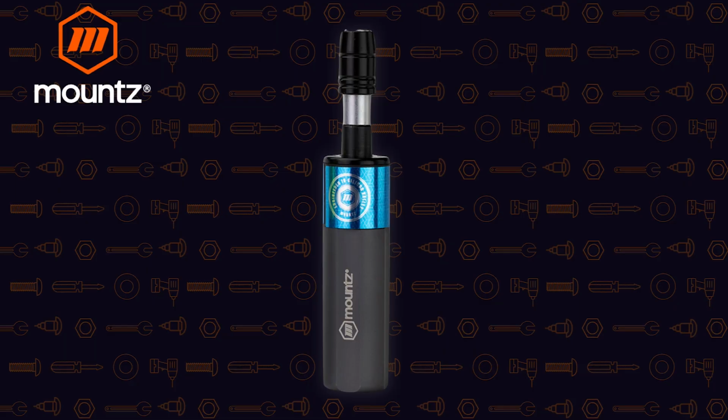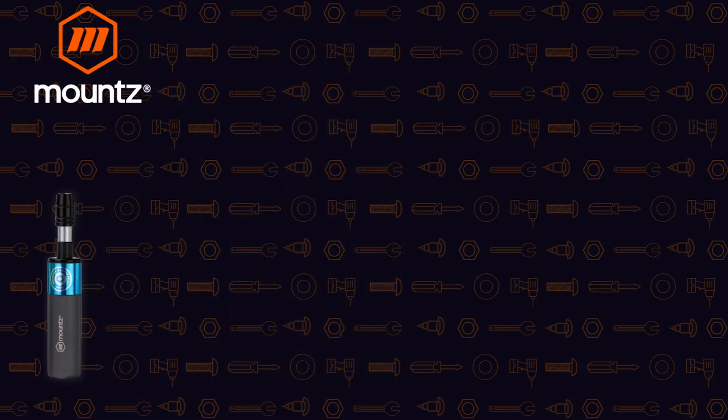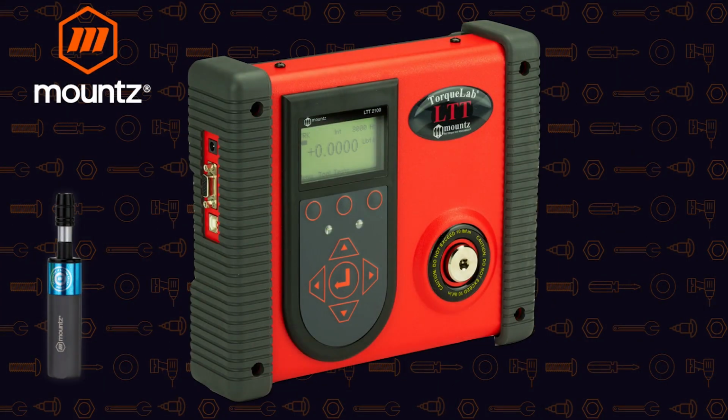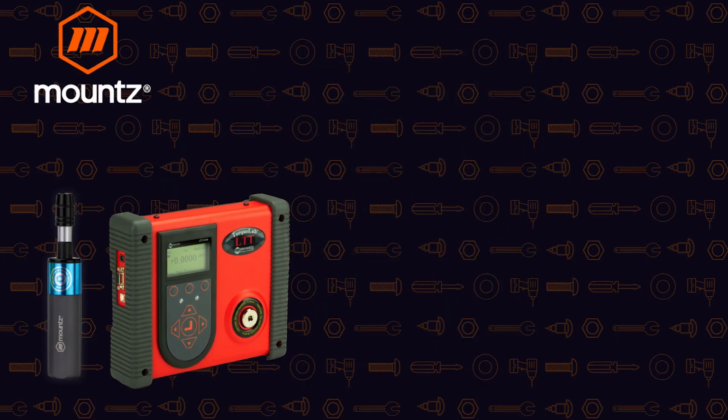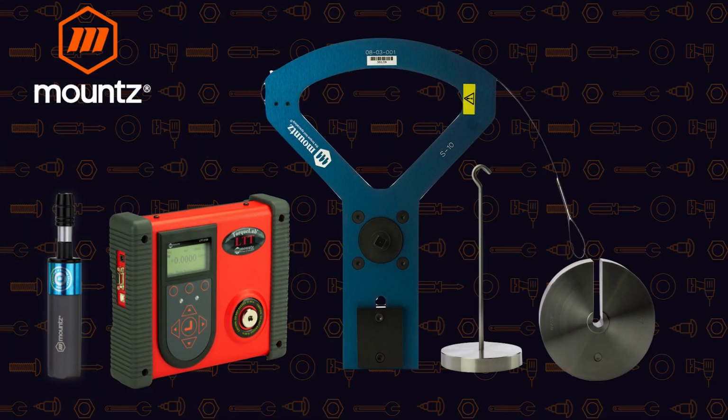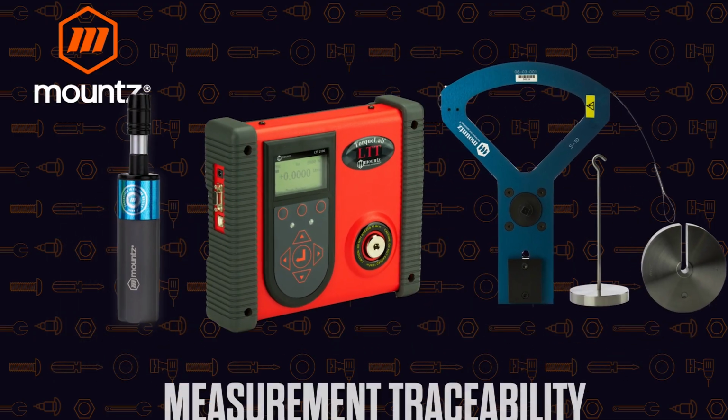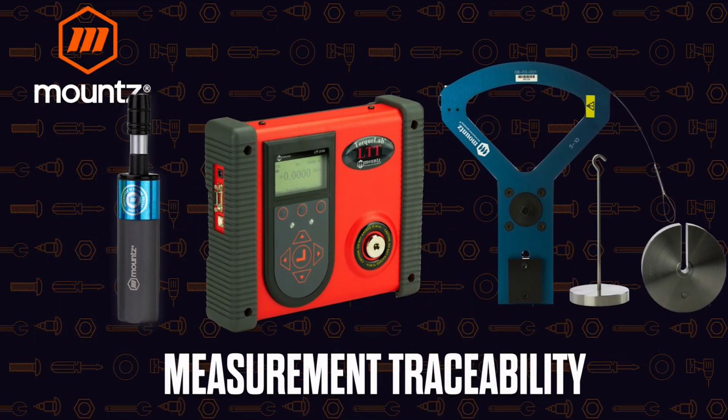And so our torque screwdriver gets calibrated on a torque analyzer. That torque analyzer is calibrated through the use of segment arms and dead weights. And this is all part of a measurement traceability that we have. And so we know that for the screwdriver, we could trace that all the way back to the dead weights.